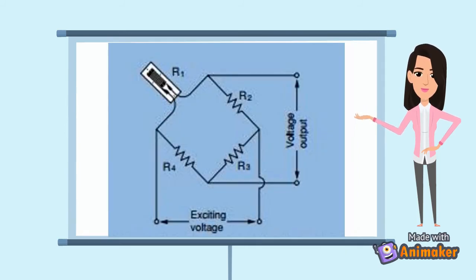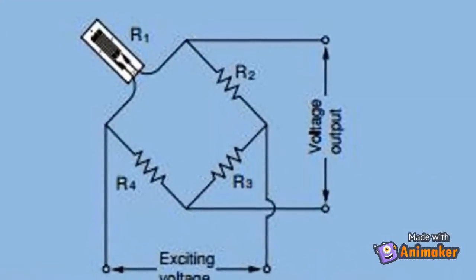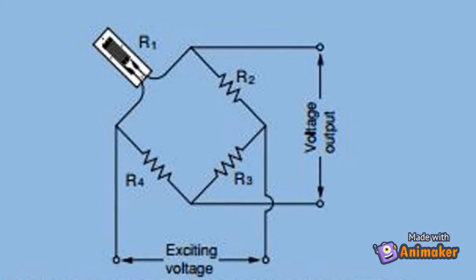This is the strain measurement circuit. Due to the extremely small resistance change, the Wheatstone Bridge is used to convert the resistance change to a voltage change. R1 is the strain gauge. A strain gauge consists of a flexible insulating backing that supports a metallic foil pattern. The foil can deform and change the resistance. Strain gauge resistance is typically in the range of 30 ohm to 3000 ohm.